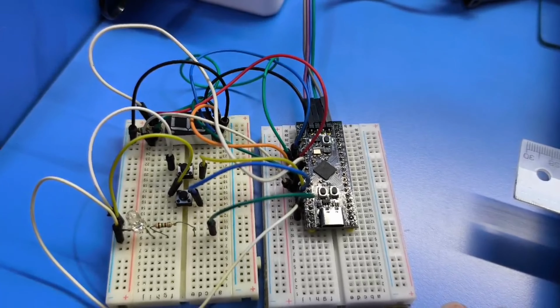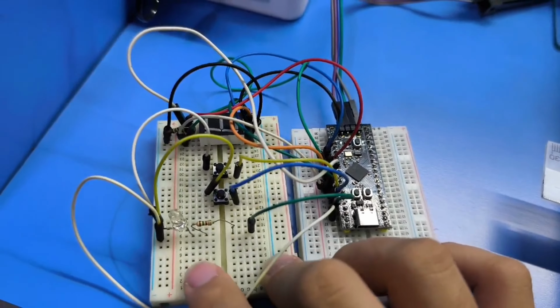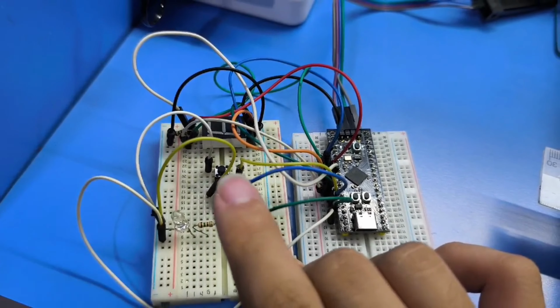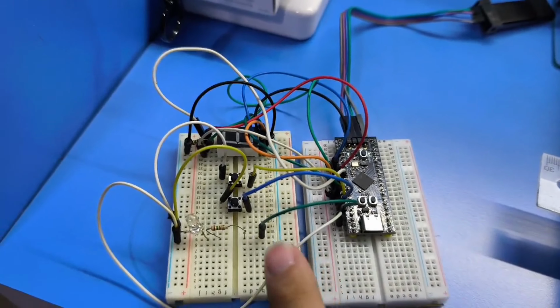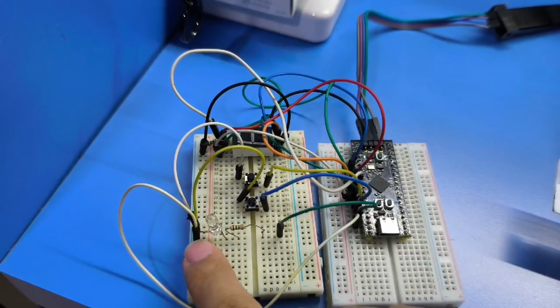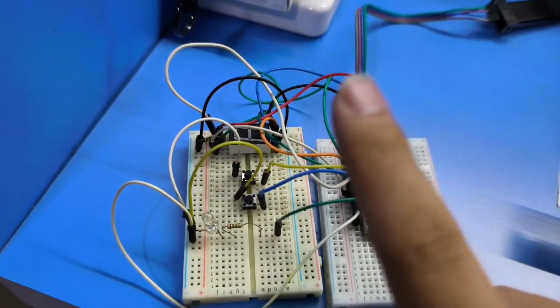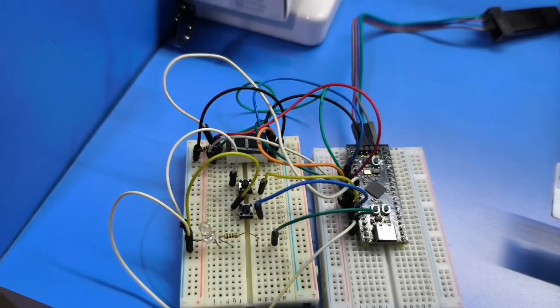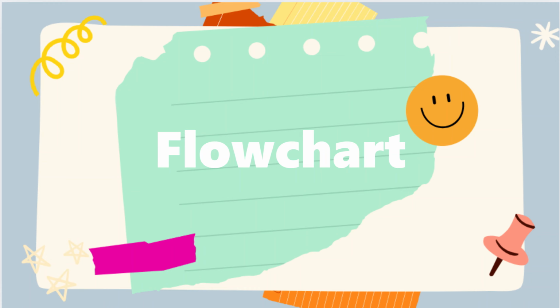This is the hardware setup for our group assignment. This is the black pill. This is the STM32, and this is the LED with resistor, push button, and 7-segment display with resistor as well. This one is set to active low, so we set to VCC for the positive side. For the button as well, we set to VCC to make it active high, and lastly, the 7-segment display we set to VCC to make it common anode.